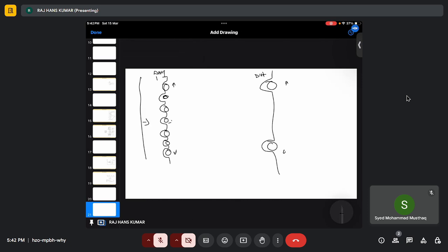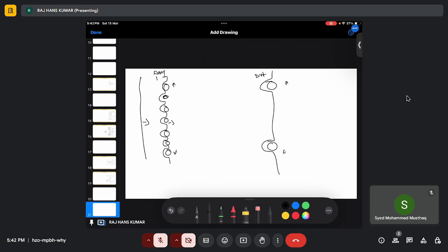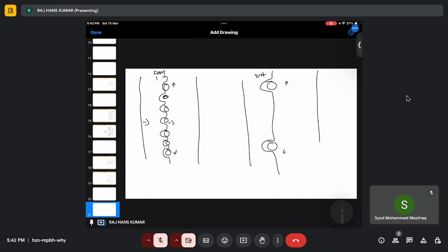First it comes here after time t2, and after time t3. So again, the distance between the precipitates will also define how much strength, or how much energy is required to move the dislocation from one point to another, from one to two. So again, the distribution of precipitates will also define our mechanical properties, or the yield strength, right?